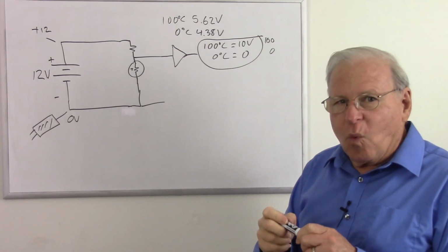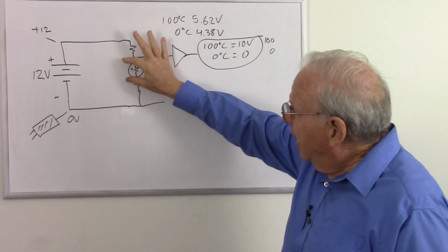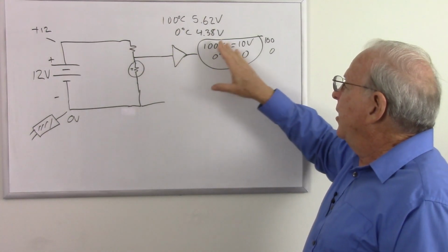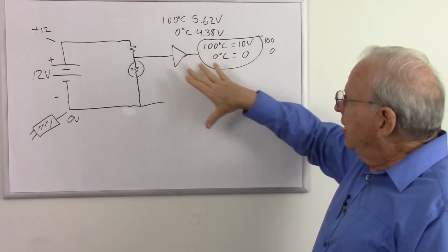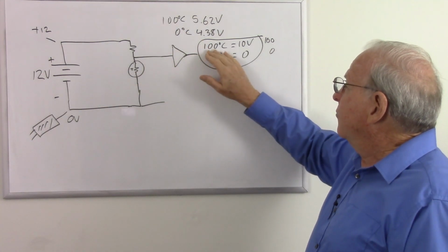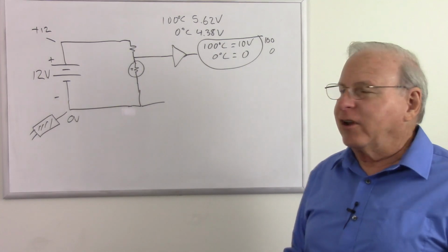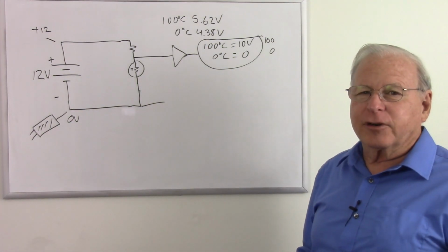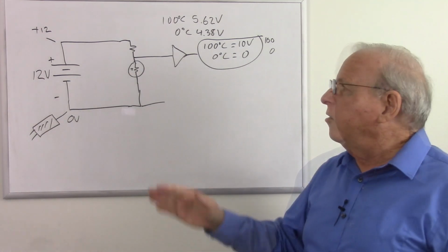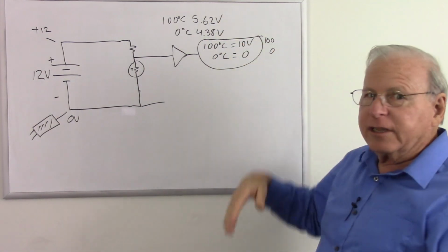So that's a way of using an analog circuit. We're taking a narrow range of voltages from this thermistor circuit and turning them into a wider range, and using some bias such that we get some nice numbers that we can convert into some simple voltages here to display as a temperature. So that's one possible thing you might do with an analog circuit. But notice we can have any voltage in this range here and spread that out to any voltage in that range.